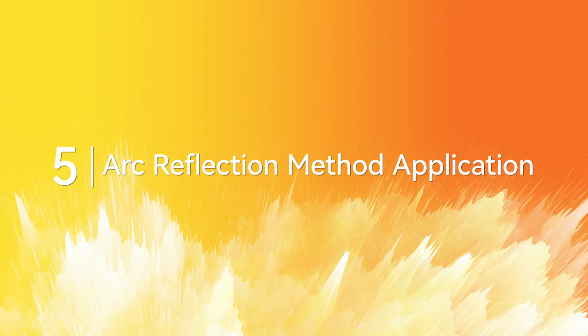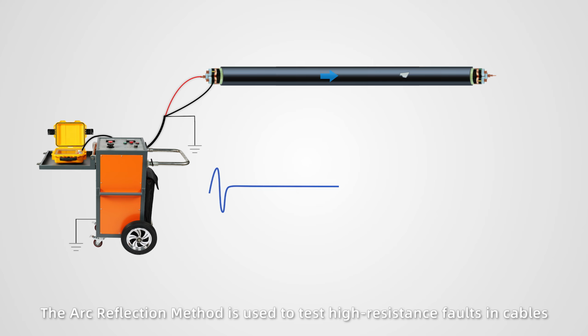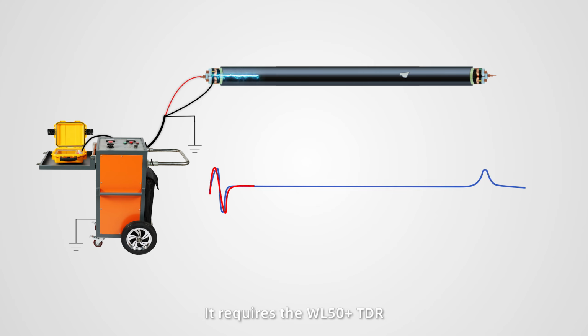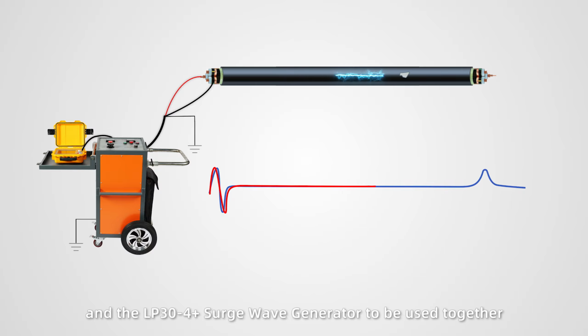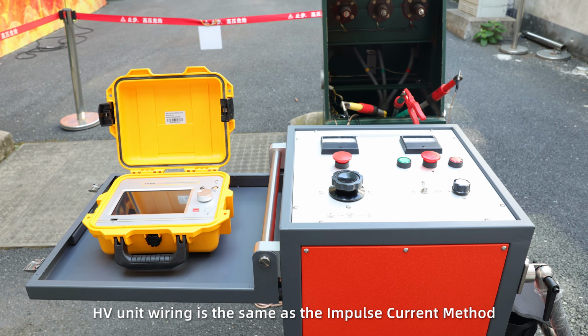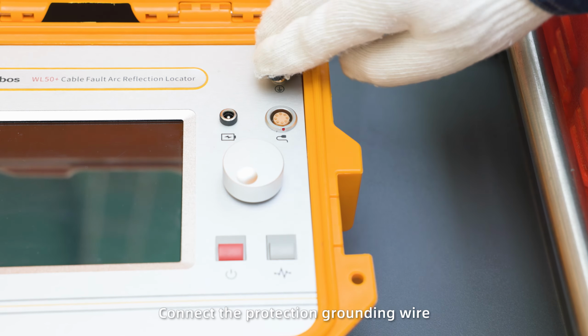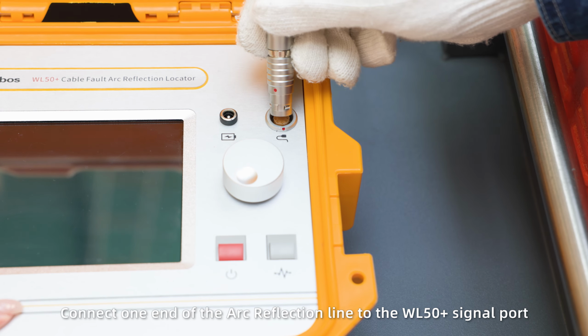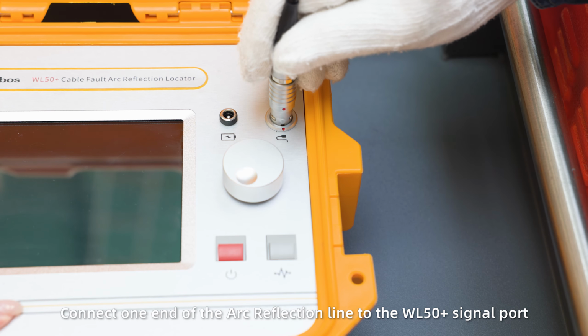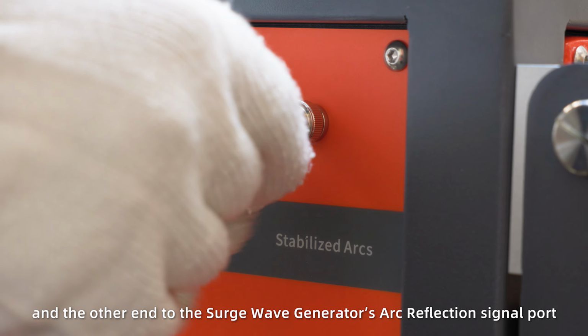5. Arc reflection method application. The arc reflection method is used to test high resistance faults in cables. It requires the WL50 TDR and the LP30-4 surge wave generator to be used together. HV unit wiring is the same as the impulse current method. Connect the protection grounding wire. Connect one end of the arc reflection line to the WL50 signal port, and the other end to the surge wave generator's arc reflection signal port.